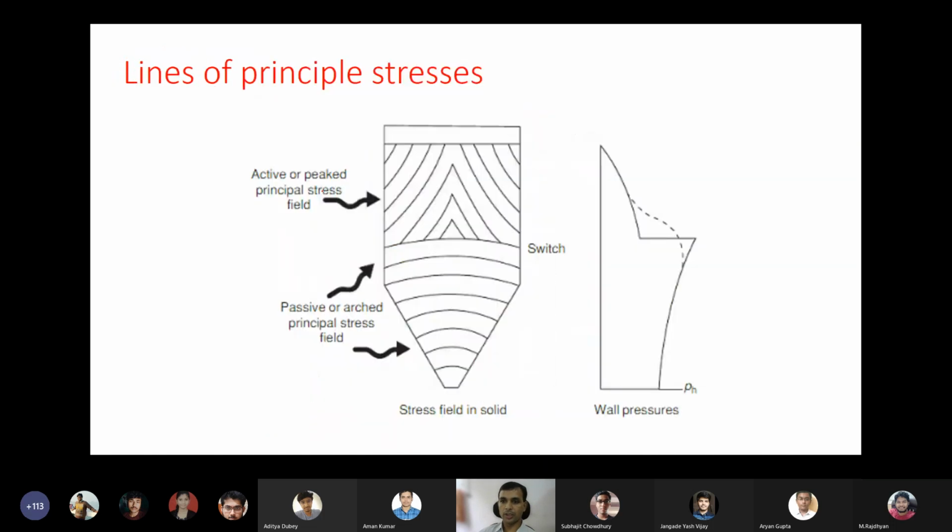The last point, which I explained here, is the stress field during the emptying, right? As I said, below the horizontal part of the hopper, most of the load distributes towards the wall, but in this top section, the load distributes in the vertical direction, with less load on the wall.